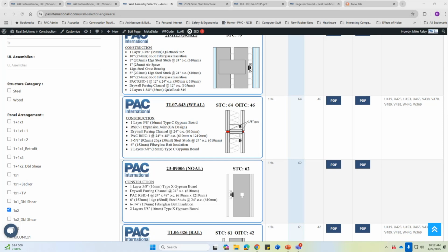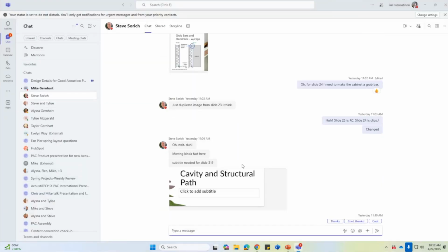Mm-hmm. Okay. And the last point was regarding the staggered studs. We had a large post facility in Burbank where between the edit rooms we used staggered studs because we were short on, let's say, space. And so when the inspector came in, he made us tie them all together in three heights, which basically broke our isolation and created a nice structural path. So it's like nitroglycerin, some of the stuff we do. Know what you're doing before you do it, and we were kind of blindsided by that inspector.